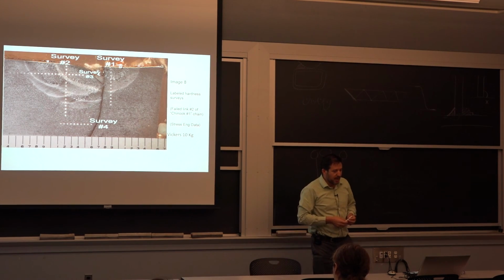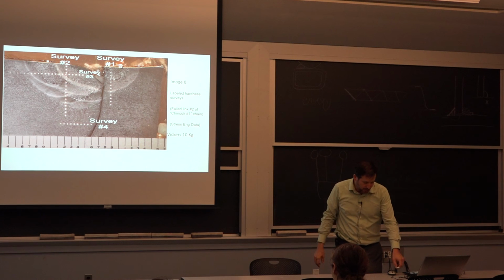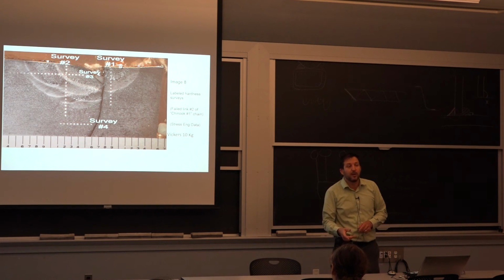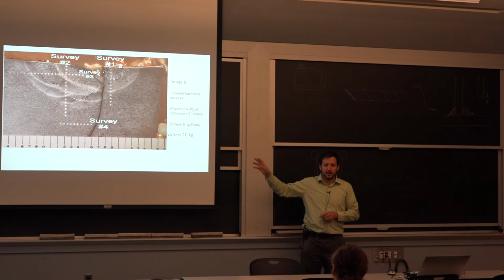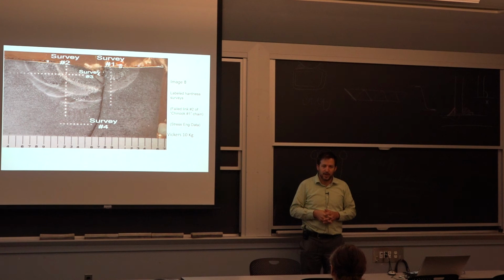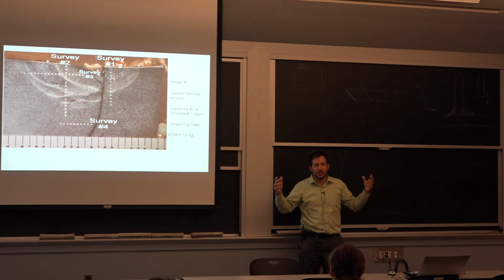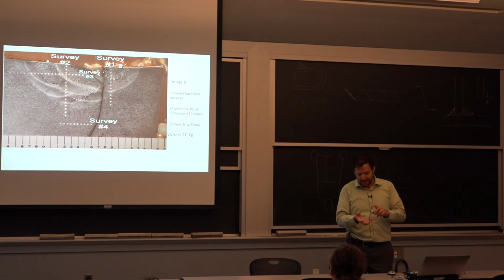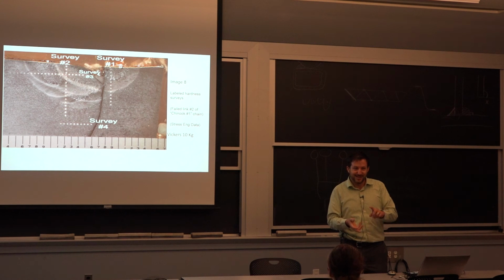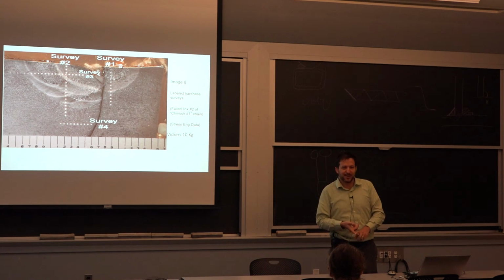So after the fact, I think the manufacturer admitted that they did the repair weld after all the quench and tempering. It's completely unacceptable. Had they done it the other way, no failure. So the problem really is that they had essentially martensite in the final product, even though the entire process was built around avoiding it. So it's very unfortunate, but I figure this really ties into deformation or welding and the impurities, and you get it all in here.